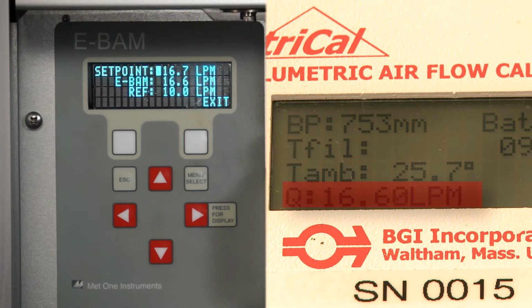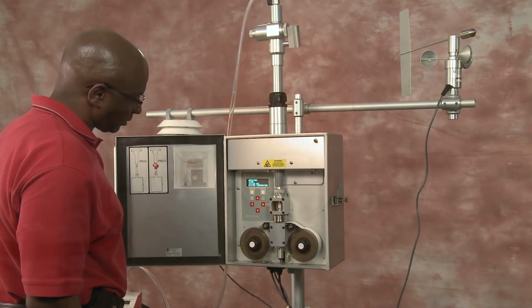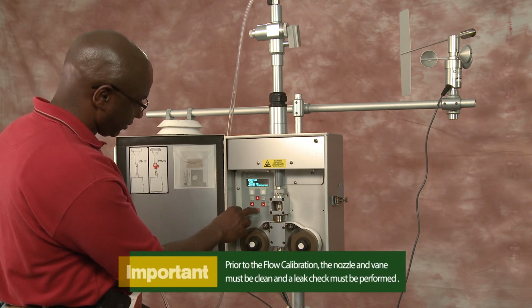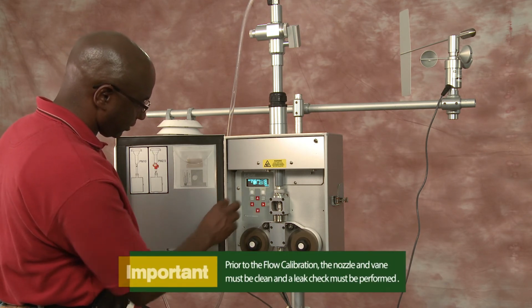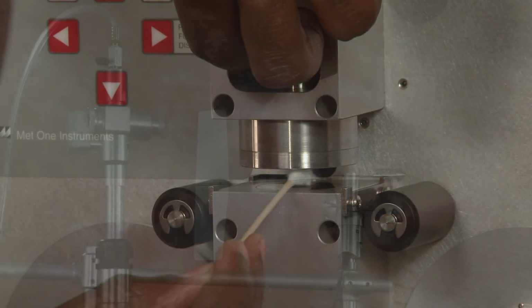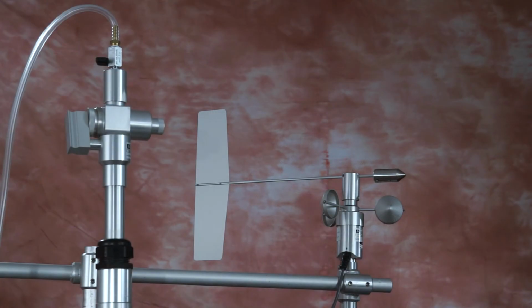Most agencies adopt tighter standards. Met 1 recommends that the flow be maintained within plus or minus 0.2 liters per minute, which is well within the unit's capabilities. If a flow calibration is required, first calibrate the temperature and pressure, since the EBAM uses these parameters to calculate flow. In addition, the nozzle and vane must be clean, and a leak check must be performed before the flow calibration. You will need to remove the PM10 inlet head and install your NIST traceable reference standard flow audit device onto the top of the EBAM inlet tube to measure the flow.